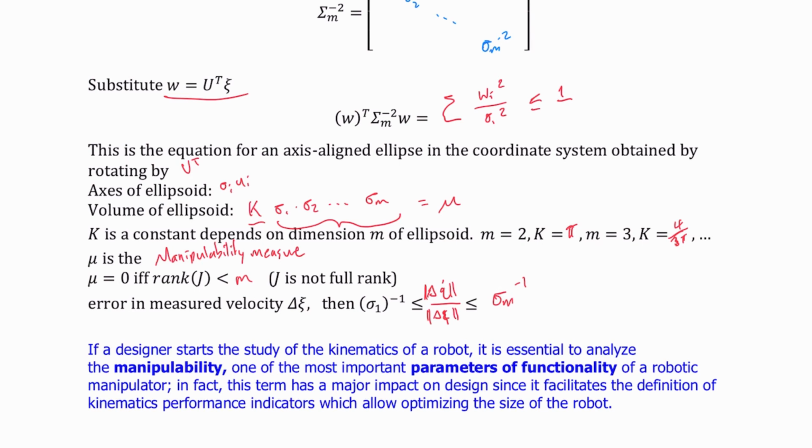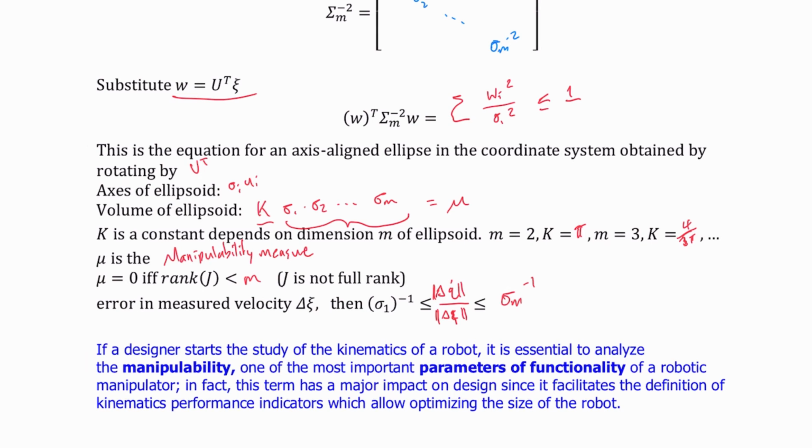If I am in the part of my manipulability ellipse where it's very much like an n-dimensional sphere, then I'm going to be able to bound my velocity well. So this is good. If I get into an ellipse that looks very cigar-shaped, then that's bad. This measure isn't going to do much anyway. But this manipulability measure tells you what's the best place to put my workspace or my object that I'm working on. Where do I have the most ability to move in arbitrary directions?